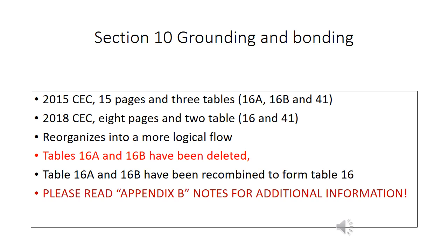For an excellent explanation on grounding and bonding, please read Rule 10-002, but in brief. Grounding: its intent is to reduce the shock hazard between earth and non-current carrying metal parts on equipment and limits the voltage rise on the neutral conductor. Bonding: bonding conductors carry fault current and equalize the ground potential rise between different pieces of electrical equipment.